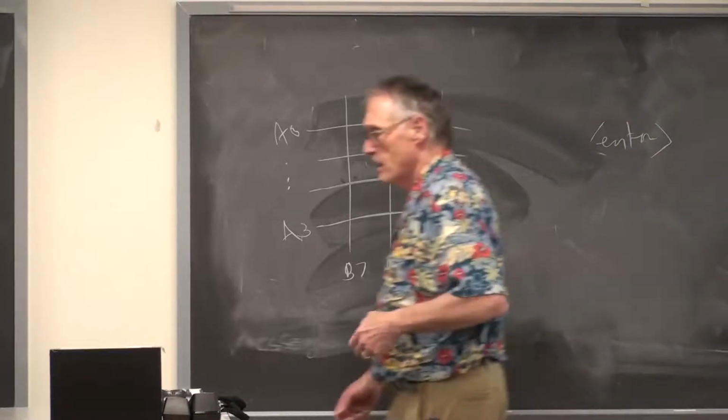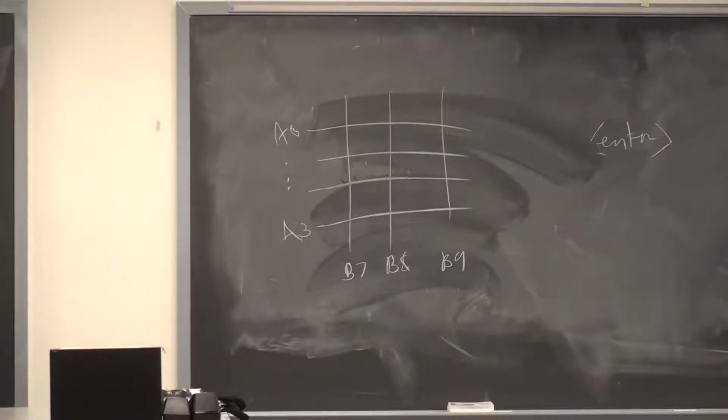So I went back and looked at the documentation for the big board. PIC32 target boards. We scroll down a ways here, and we find that I thoughtfully sorted all of the signals used by port number here so you could figure out what's already in use. Oh crap, RA0, RA2, and RA3 are already in use. Or are they? Are they on your board?